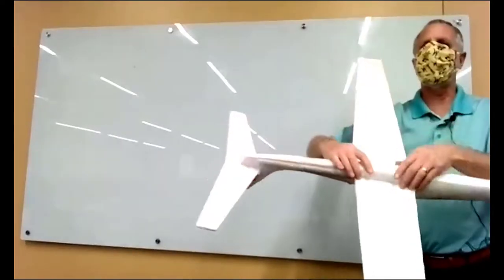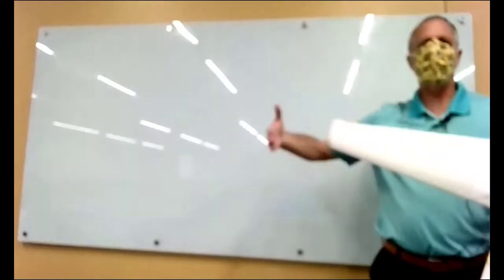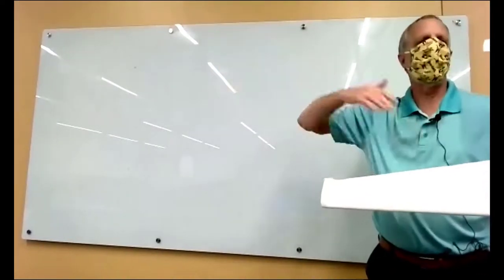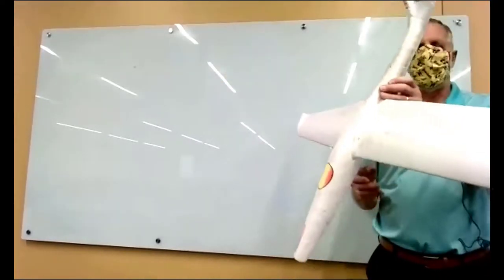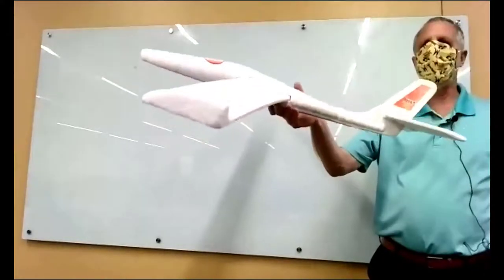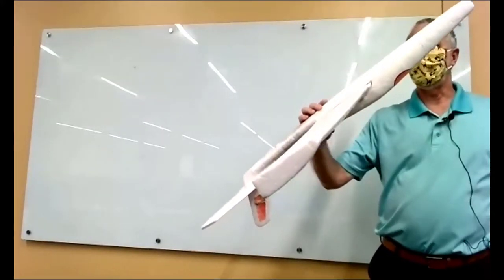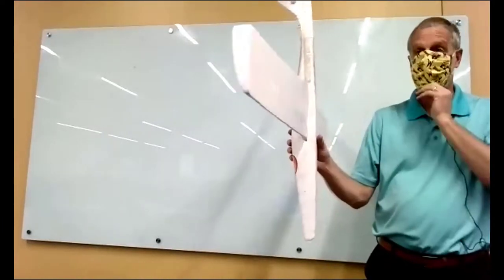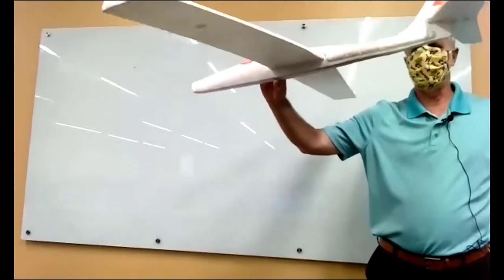Just like when you have a mass spring damper system, the damper in there slows down the velocity of the mass. If you take the damper away, it bounces back and forth forever because the spring compresses. You just get a trade-off of kinetic and potential. There's no dissipation. So this effect that we're going to be talking about now is a pitch damping term. And it will be really important when we solve the differential equations for damping out the motion of a pitch disturbance and a pitch rate disturbance.